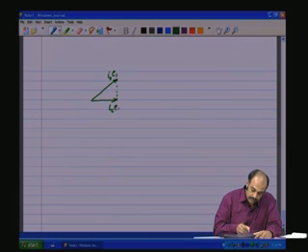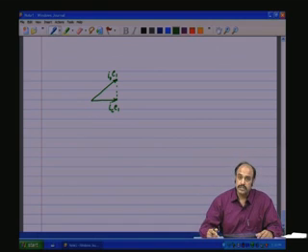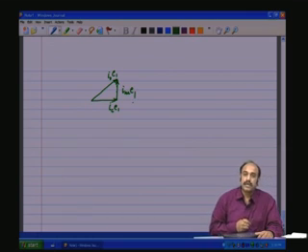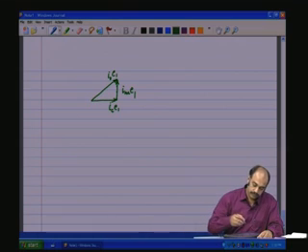Ic into E1 is the active power, that is the loss component, which is drawn from the source, and Im into E1 is the reactive power that is drawn from the source for setting up the magnetic flux in the core.